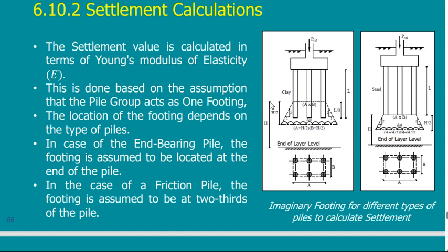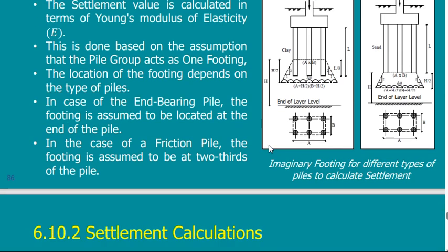Here the thickness is from this point to this point. Calculate the settlement of this compressible layer, as if you are solving a settlement of a shallow foundation. Either I give you the edge, because I give you the end of the compressible layer, or if I don't give you the edge, you will assume it to be twice this dimension. Which dimension? The smaller dimension, twice the B.